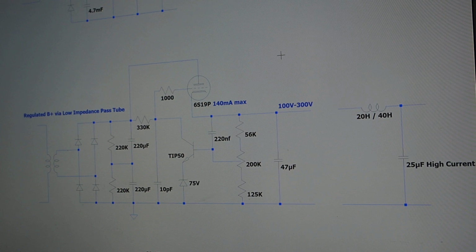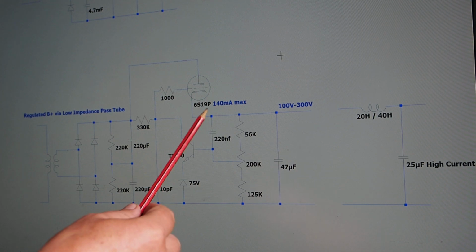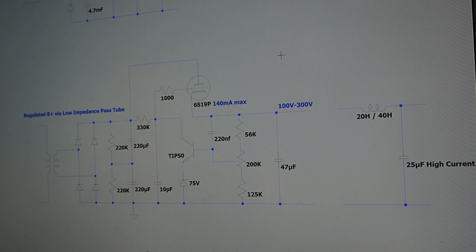Does it have an impact on the sound? Yes, it probably will. I will do a comparison probably soon, with and without, just to really reacquaint myself with the difference. But it's at a pretty high level the way this is constructed, and with this tube. I've in the past also used the EL86, which has about 830 ohms plate resistance, and just used 2 of them. It's a pretty good solution.